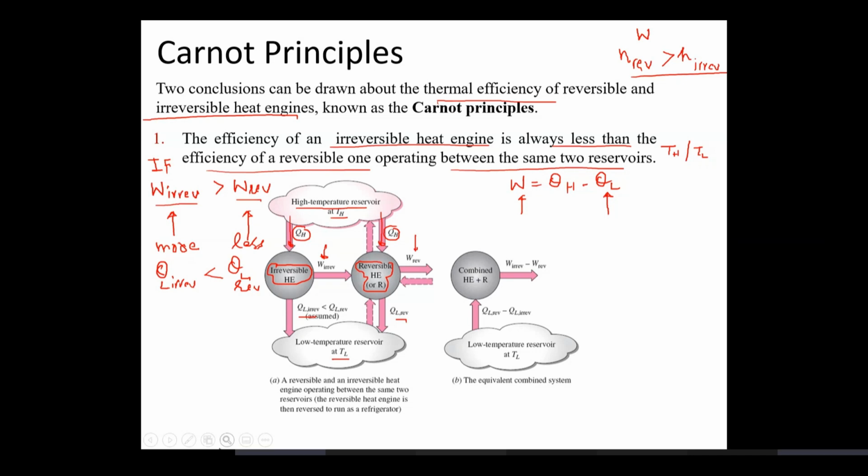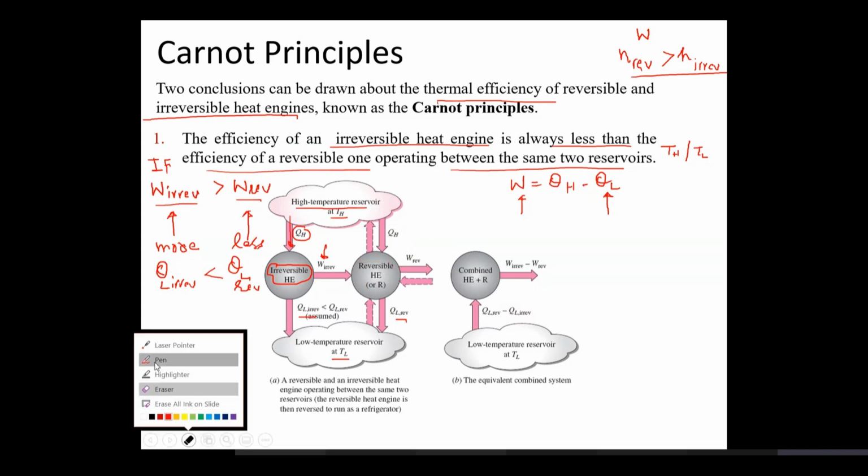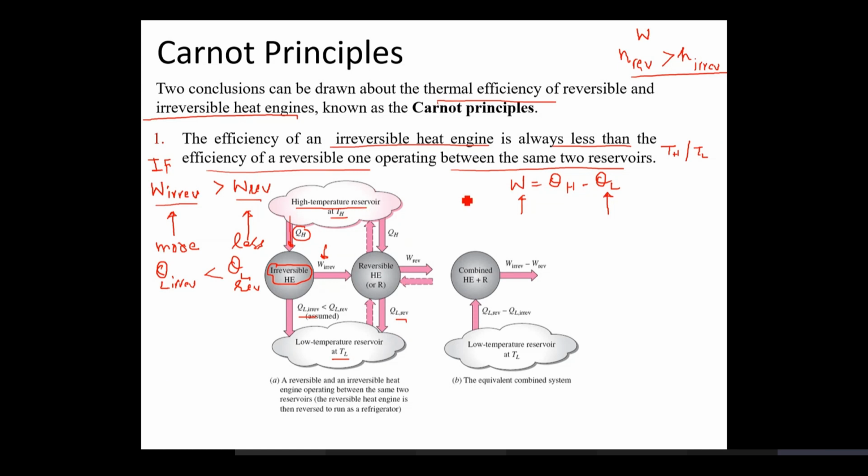Yes, sir. Now, let's say I am talking about the reversible heat engine. Let's say I am operating this heat engine in the opposite direction. That means, since it's a reversible engine, work is being supplied to the system. It is taking QL from the low sink and delivering QH to the high sink. So I am considering it as a reversible engine working in reverse. Clear enough?